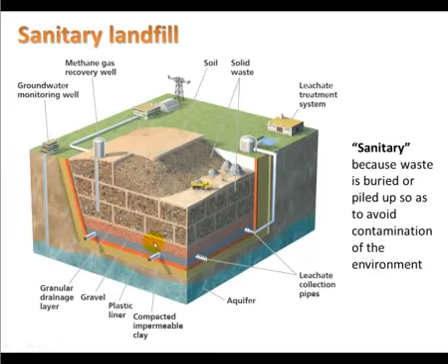Above that is where we have our solid waste, lots of it. And most of this decomposition occurs pretty slowly. We want to try to keep this waste as dry as possible so that we don't have too much water picking up pollutants. And when you have dry waste, it decomposes very slowly. The decomposition that does happen is mostly anaerobic because it's buried, so there isn't much oxygen.